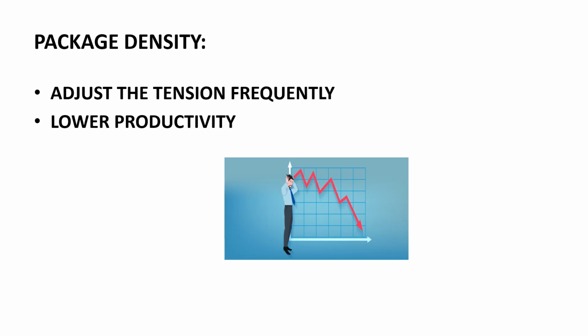Okay. So the performance of the sewing thread will be judged, but how do we really get the optimum production? In order to do so, the package density should be fixed. Yes, this should be the package density, wherein around 100 yards of sewing thread will be there.